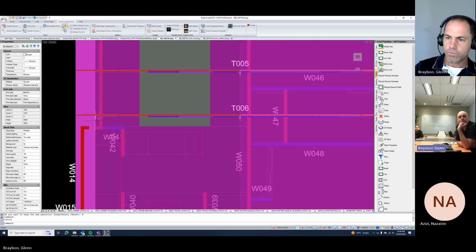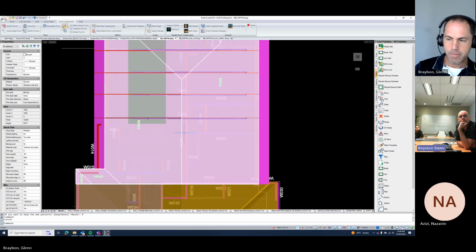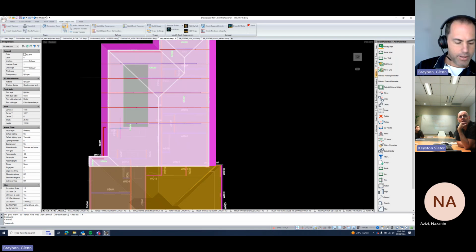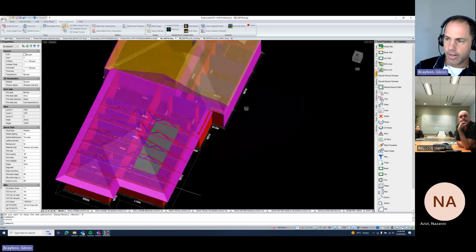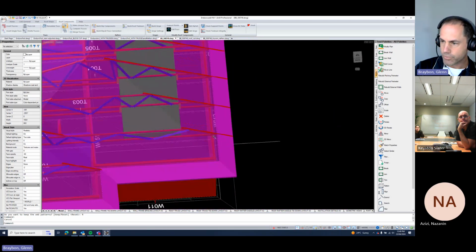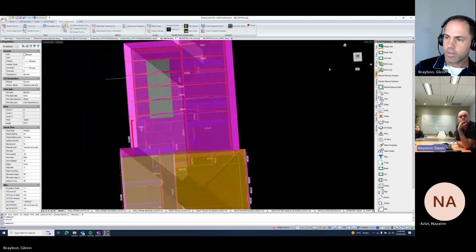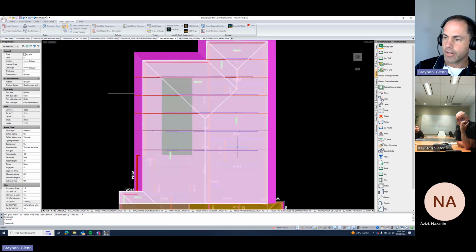Have you tried, before you build your eaves, cutting your roof block back to the internal wall and building your eaves from there? Would the heel height cause errors in this, or is it something you've not tried yet? We just do that to create a line right on the end of the truss. Yeah, I'm with you, I know what you mean. It helps the guys place their trusses better.